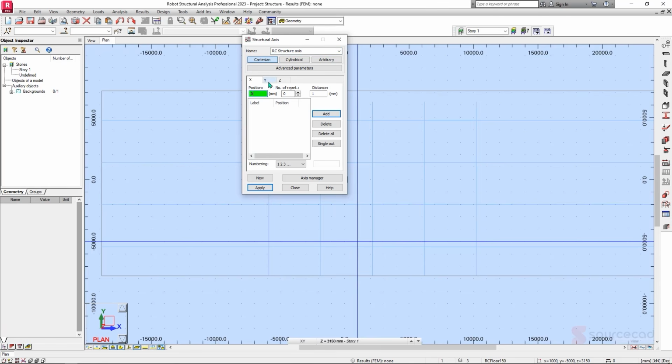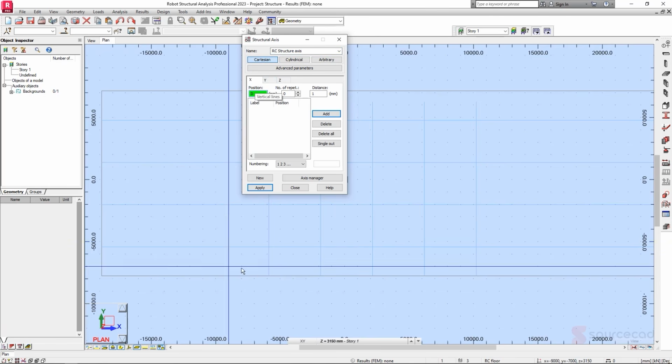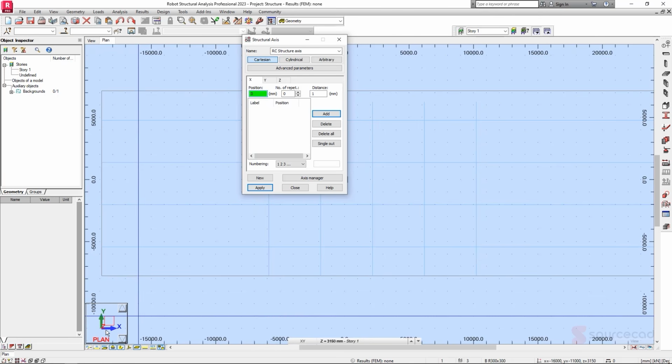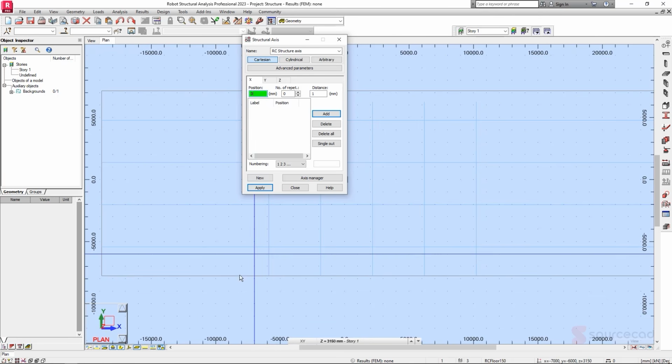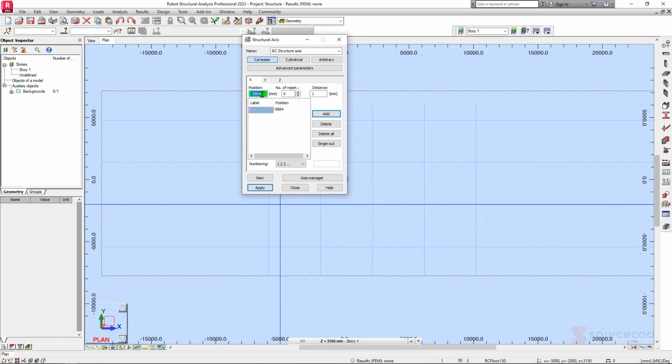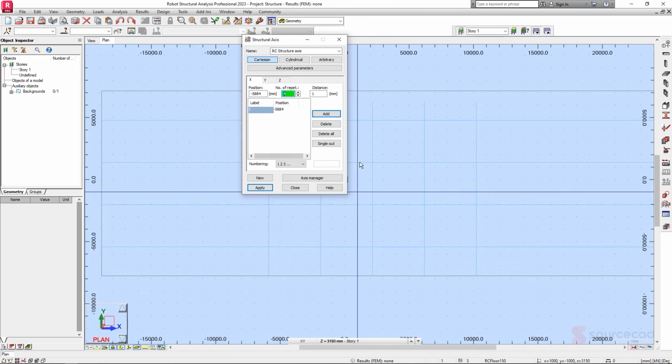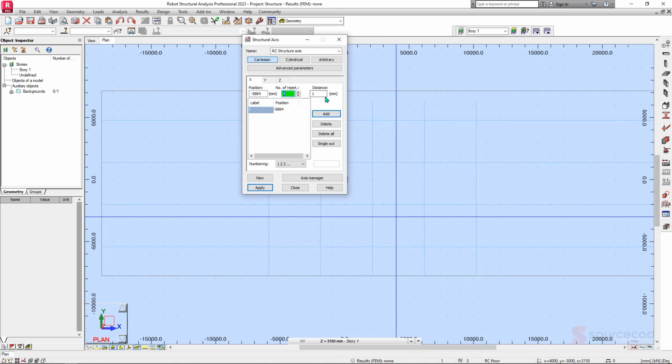And under the X, Y, Z, let's start with X. We want to create from the X direction, so from left to right, and the position will be from this point here. So you can click on it just to specify the first point, and the number of repeats from that will be 4, because now we're remaining with 4, 1, 2, 3, 4. So I'm not clicking anything here, and the distance in between will be 4025.